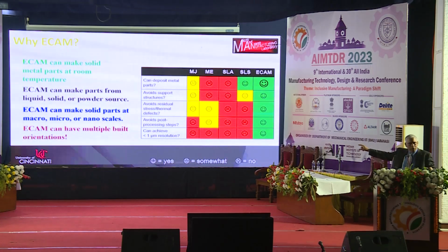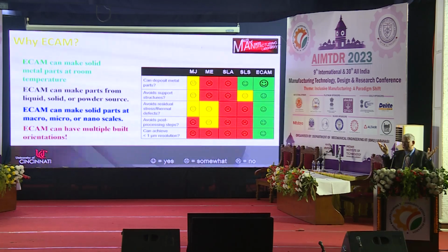And this last point that I'm saying is the real unique aspect of this. Most of the time when you talk about additive manufacturing, you'll be saying the z-axis building, right? So you will add material layer by layer in the z-axis. No such restriction here. As you saw in the earlier video, you can add in the z-axis, you can add in the x-axis, or even you can add in the negative z-axis, or it can be like 360.